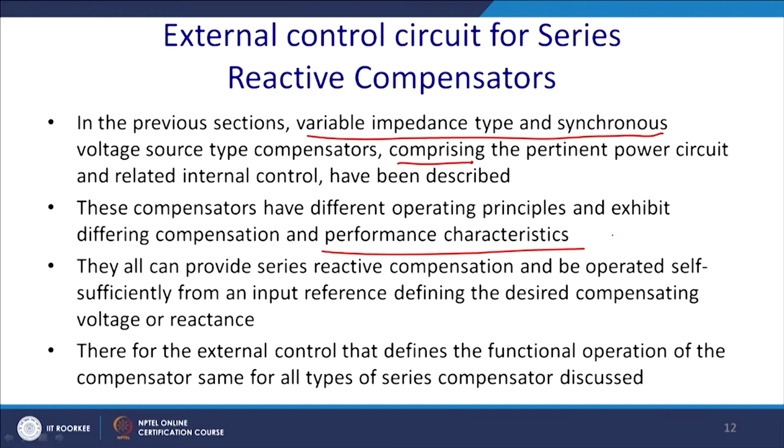So, they all can provide series reactive compensation, whether it is the impedance method or the voltage controlled method where you are injecting a voltage source. Both can control the series reactive power compensation, and operate self sufficiently with an input reference defining the desired compensating voltage and reactance.